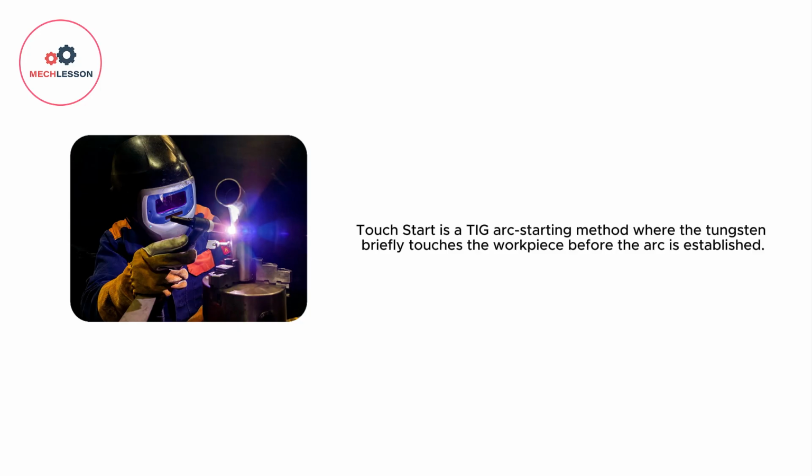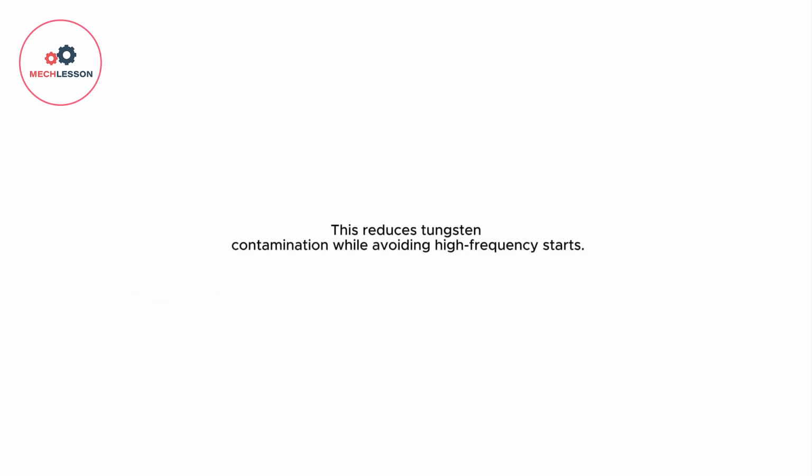33. Touch start. Touch start is a TIG arc starting method where the tungsten briefly touches the workpiece before the arc is established. This reduces tungsten contamination while avoiding high-frequency starts.